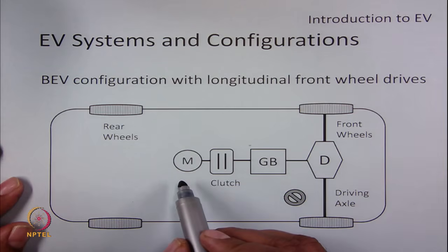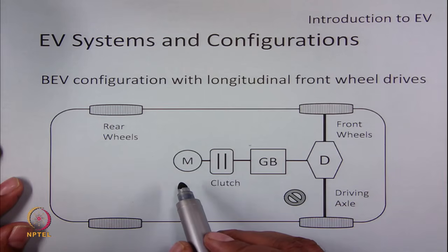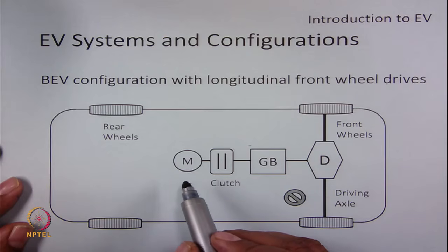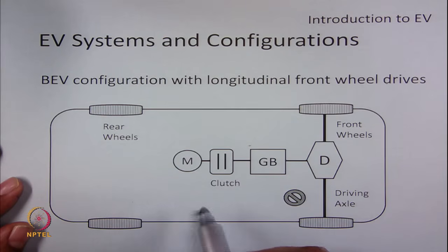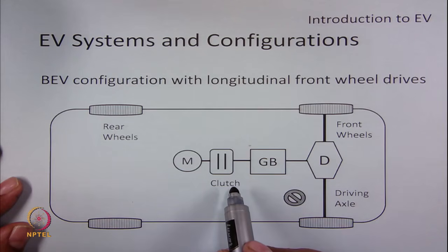So, the requirement of the motor is that it should work at full speed with the capacity of delivering the full torque. It does not need to operate in variable speed and variable torque operation, because that purpose is done by the variable gear system by means of the clutch system.